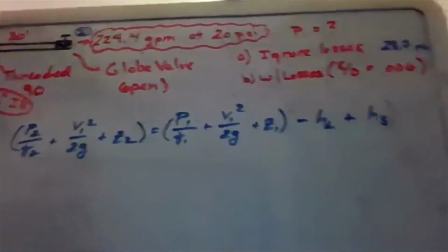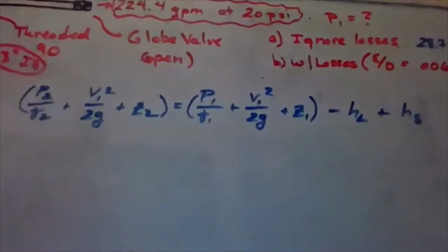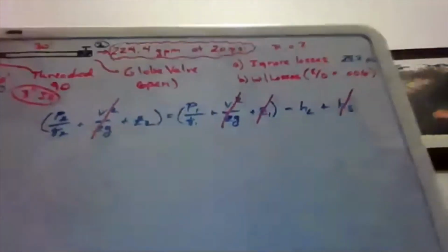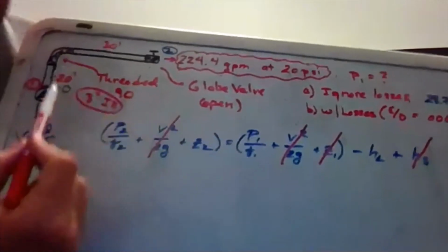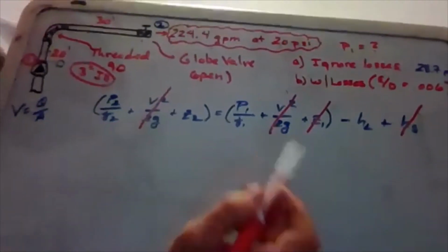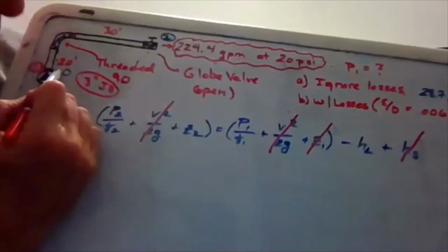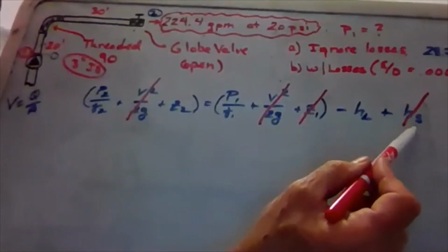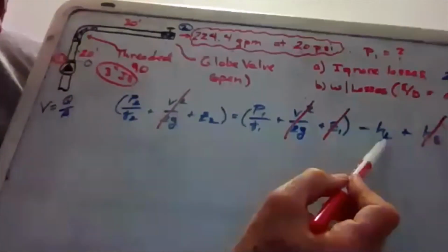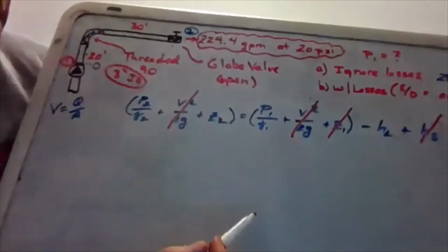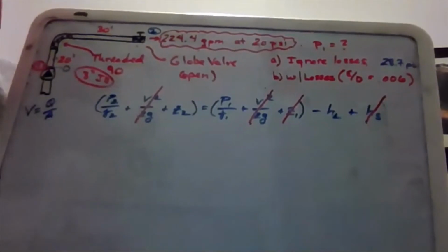All right, so first thing to do is we would love to see if you can get rid of some terms. So I'll let you think about that for just a second, and I'm going to zero out some terms to make this a less daunting equation. Okay, so hopefully you did that. If this is a constant diameter 3-inch pipe, then the speed's going to be the same all the way along. And so these speed terms don't really end up changing, okay? We decided that we're going to make Z1 equal to 0, so that's still 0. Going from here to here, there's no pumps or fans or anything like that that does work. We defined our 1 at the outlet of the pump, so we don't need to worry about the pump. But there are going to be losses. Z1 we decided was 0, so that's it. So we actually already did this problem except for the losses. So now this just becomes a process in working out the losses, and let's think about how we do that.